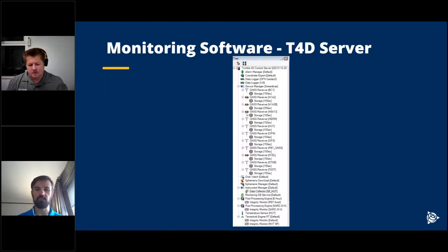Gotcha. So it's like a kind of CORS station that you're using to compare to the receivers that are on site. That's correct. TrigNet operates about 70 CORS stations around South Africa. So we've used a couple of the closest ones. Incidentally, one of them is actually at Steenbras Dam, so it's quite close. And then we use, I think, two or three other ones, which are a bit further away. Cool. And then you can see there's quite a number of stations at the moment disconnected. That's just at the aquifer project where they're busy working on the station, so they currently don't have any power.